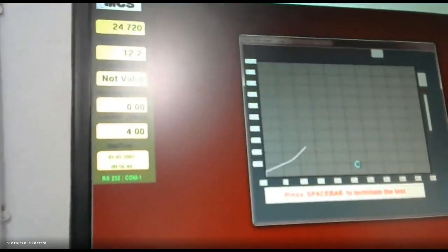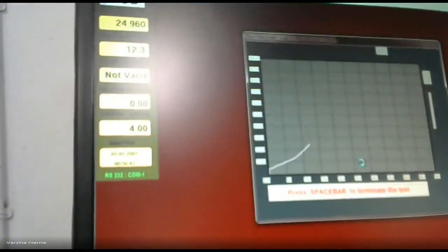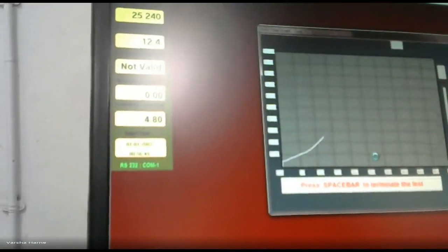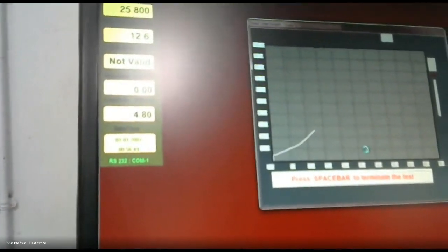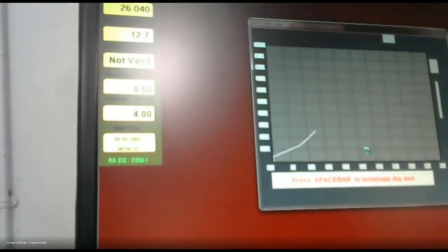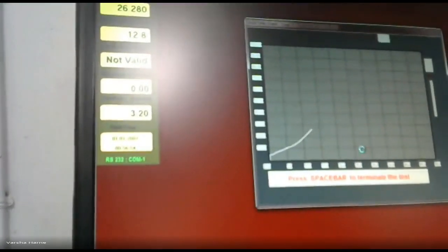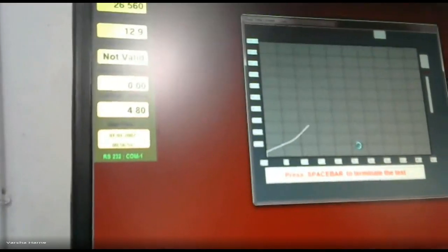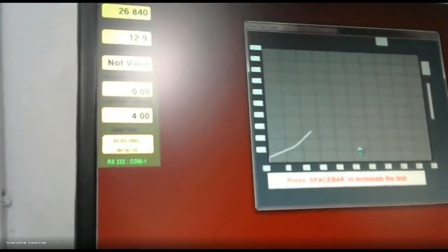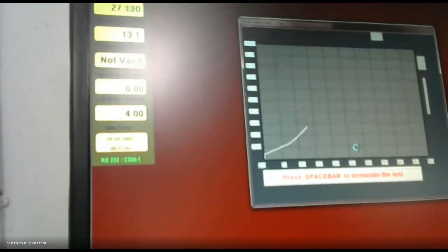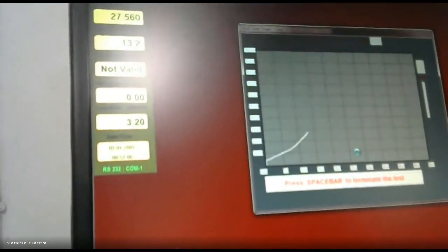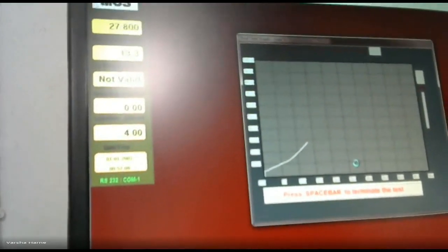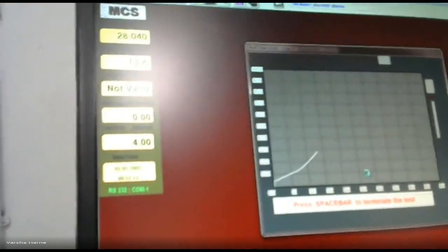After the limit of proportionality, there is another point you have to consider here, that is the yielding point. We don't know whether the yielding will start or not, so after the completion of that, we have to check it. And we have to check the strength criteria also, the tensile strength criteria.